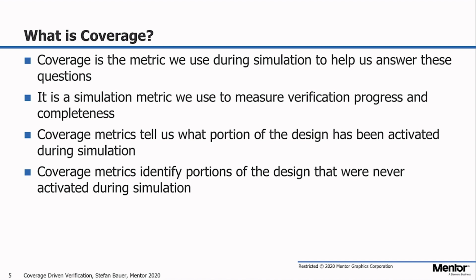Coverage metrics tell us what portion of the design has been activated during simulation. That is the controllability quality of a test bench. Or more importantly, coverage metrics identify portions of the design that were never activated during simulation, which allows us to adjust our input stimulus to improve verification.